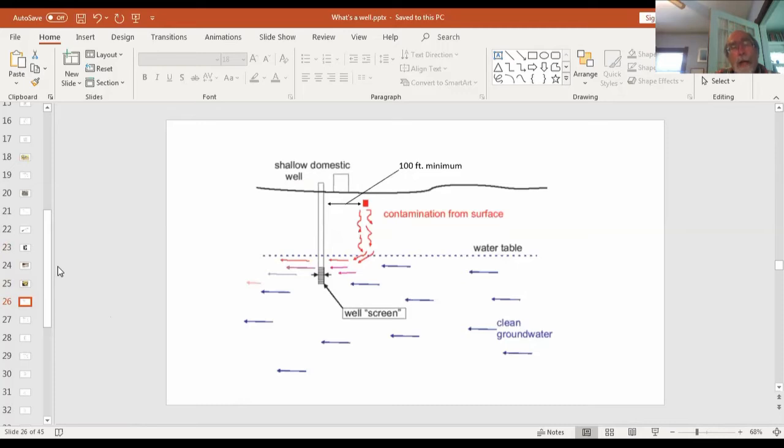The requirement from time immemorial is that you have 100-foot spacing between your well and your leach field for a typical domestic system, and that continues to be required. And I say that's just standard practice. Good practice would actually be to reverse this and put the well on the up gradient side, so that when you did hit the groundwater, it was all swept away from your well. So there's that basic 100-foot minimum. But as we can see in our diagram, that's of limited usefulness as you begin to look into the subsurface.